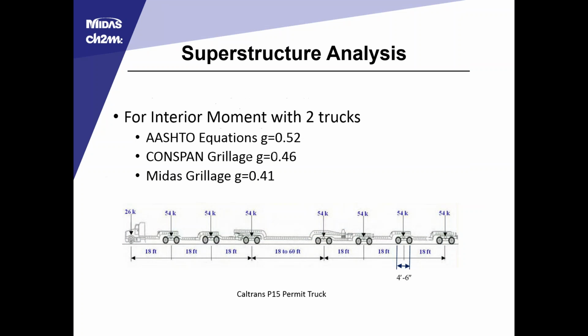It was possible to use the CONSPAN grillage analysis, which revised the design, although that's a little bit behind the scenes and harder to tell. So just for comparison, we did a MIDAS grillage analysis. And here's one example of the interior moment with the two trucks: AASHTO equations, CONSPAN grillage, and then the MIDAS grillage, all within the same range, but MIDAS was slightly less conservative and allowed for a workable design.